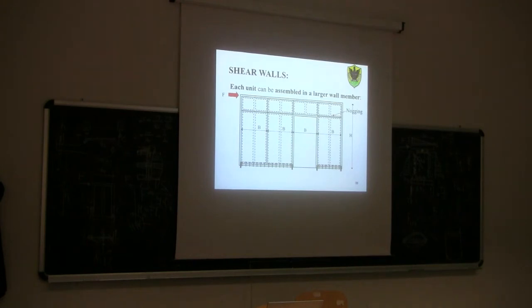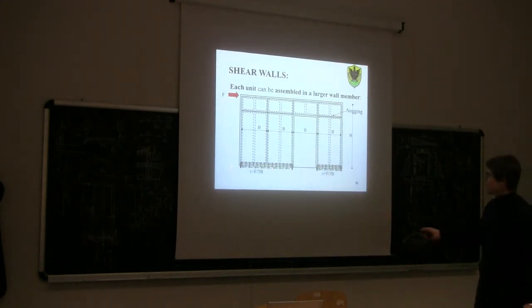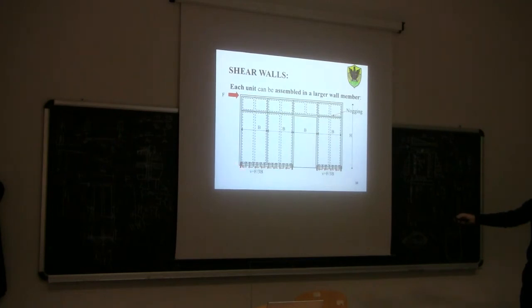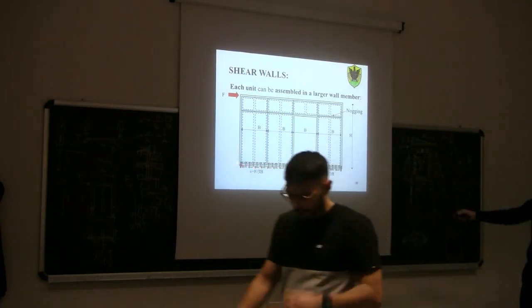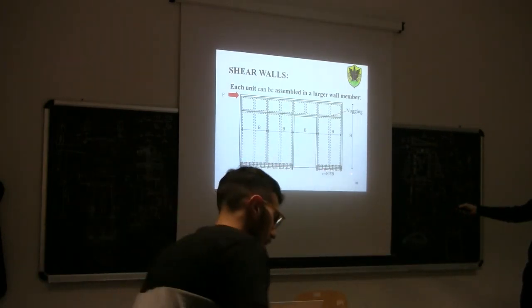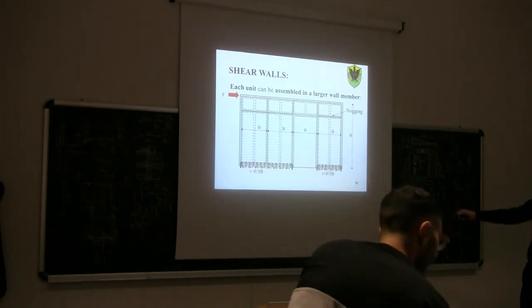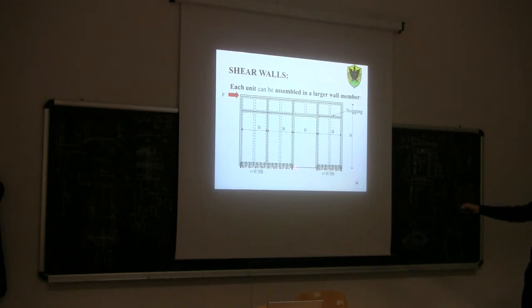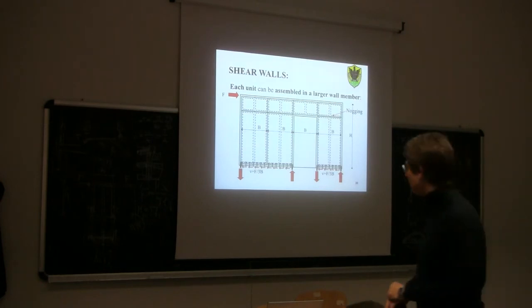So when we apply a horizontal force here, F, then from equilibrium we will get some shear forces. So the member resisting shear will be basically 3 units. So V will be F divided by 3B, because 1, 2, and 3 here we have a wall. And then we need to find out the vertical component in the outer studs.